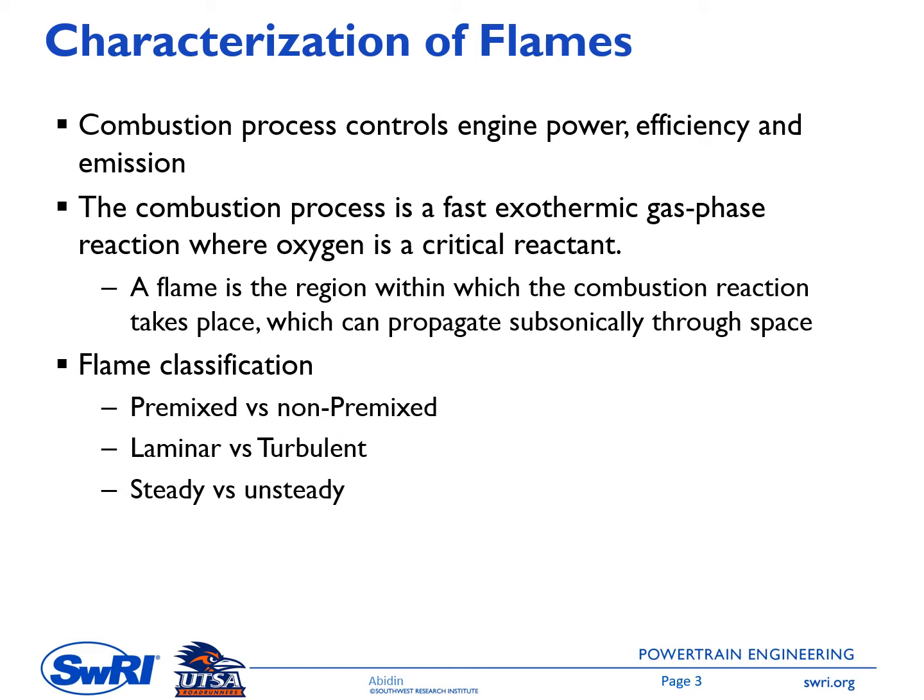In the diesel engine, fuel is injected into the cylinder, and inside the cylinder we have air, or maybe air plus EGR, already at high pressure and temperature, because this fuel injection is near the end of the compression stroke.